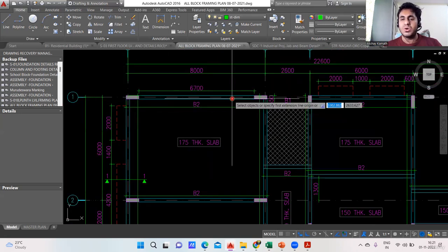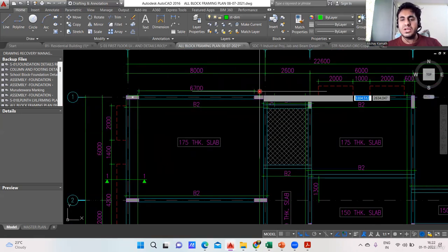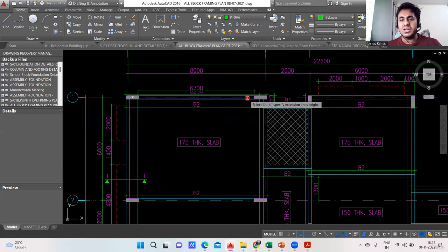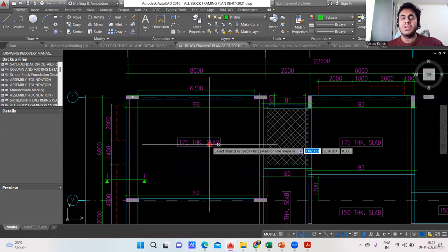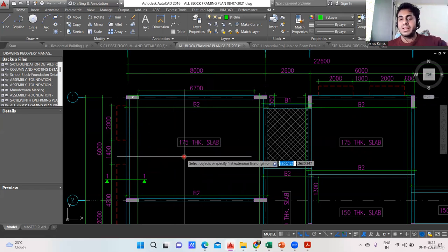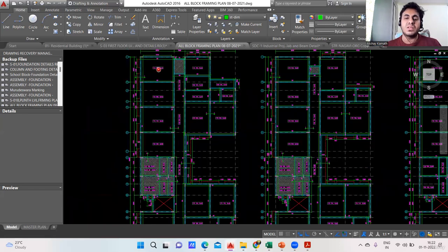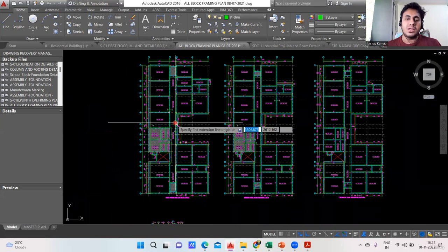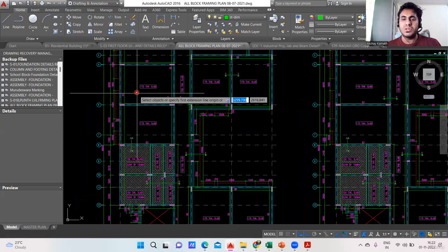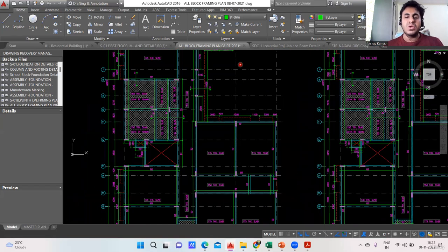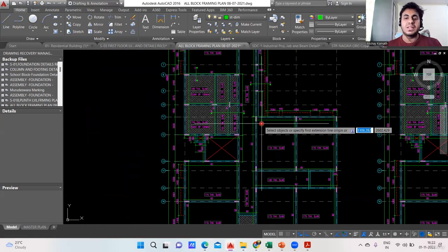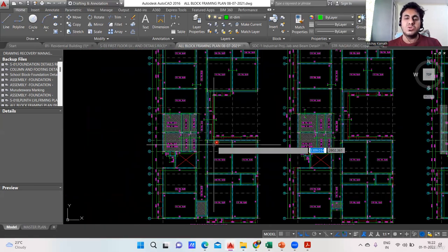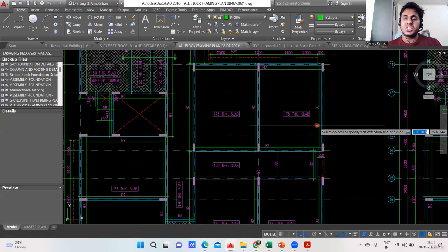Now you have the sizes. With this, you can find the concrete quantity. Then you will have this outside shuttering. This becomes the inside shuttering, where you have a slab coming. The thickness of the slab is 175. Overall depth was 750, so 750 minus 175, and you'll get the answer. In this way, can you not do the complete estimation for this building? You can do that. You getting my point? Only where you have to be careful is in the beam shuttering. That is the only bit complicated. You just need to check whether your beam has outside shuttering or inside shuttering.